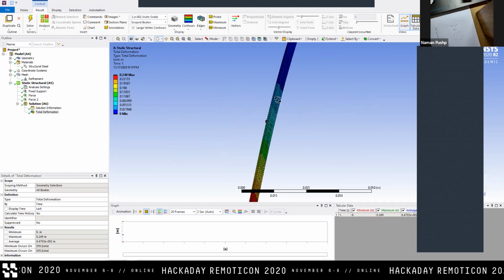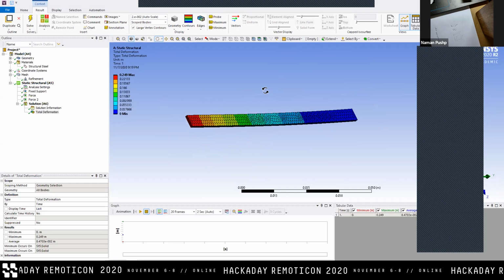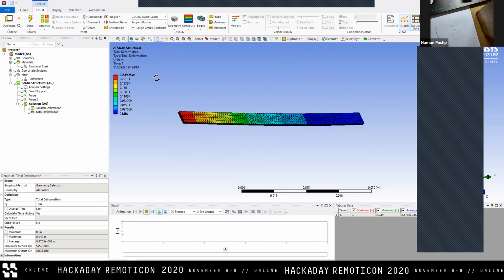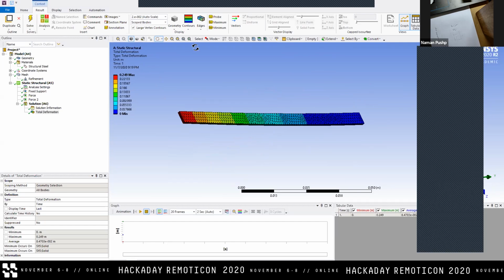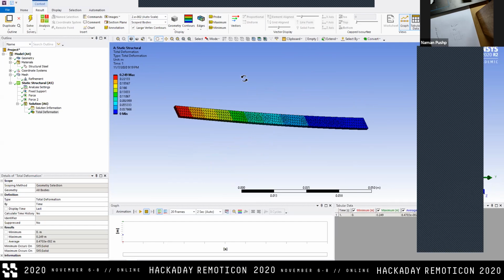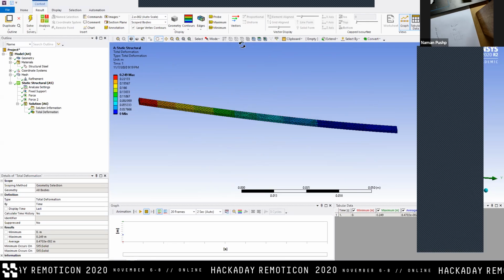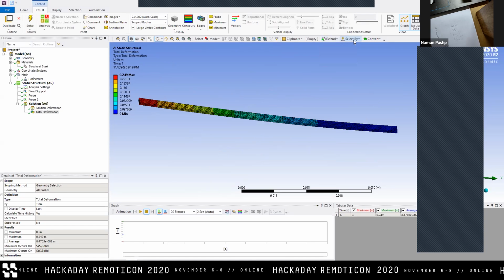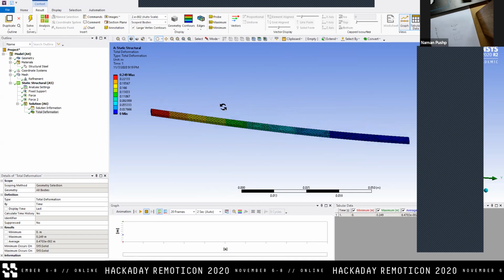Unfortunately, with stuff like ANSYS, you won't really get your super dramatic results. You're going to have to realize that if this is moving up 0.249 meters, it will not survive. There are other software which I think may give you that snapping, but it's quite hard to get. But you can tell with the deformation that it probably would not survive.